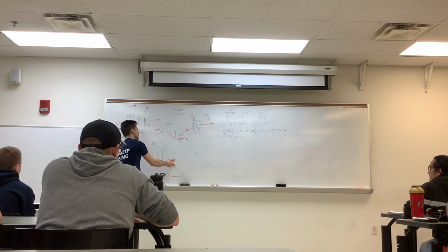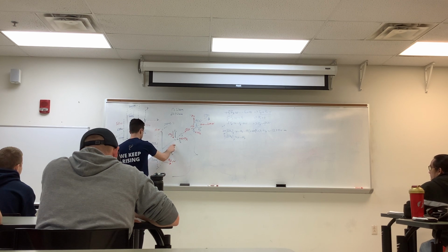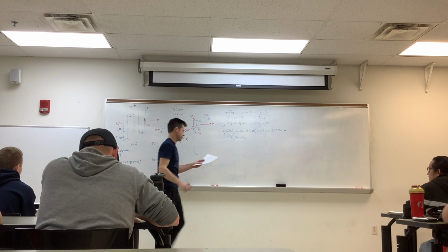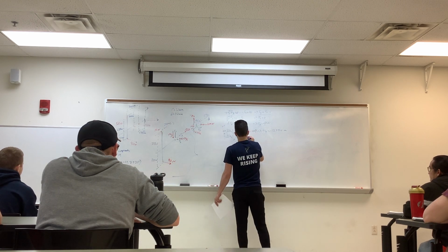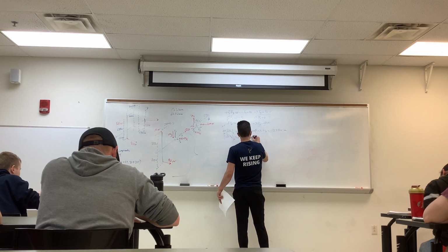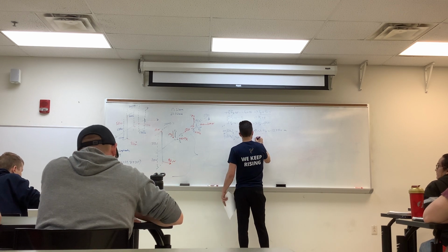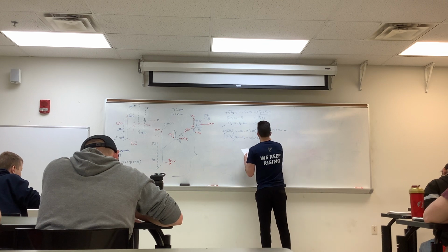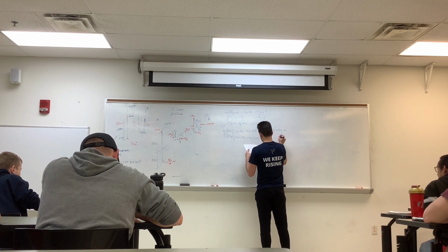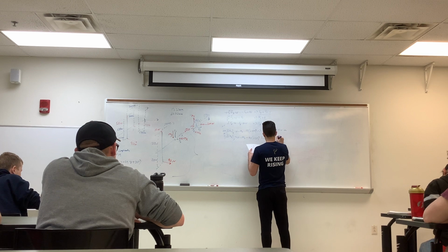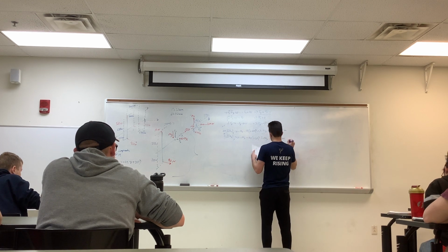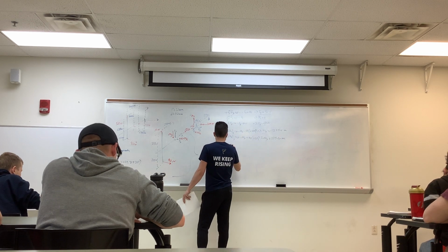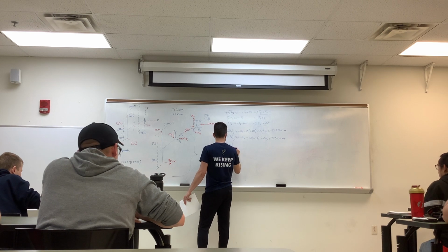This 90 newton force does, and it's at a moment arm of this 250 millimeters. And it's positive 90 newtons and then 0.25 meters. We get our My to be equal to 22.5 newton meters.